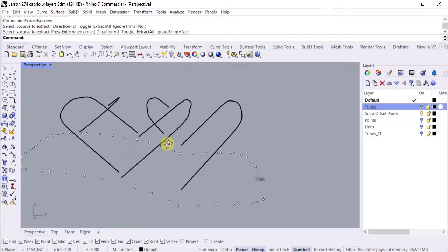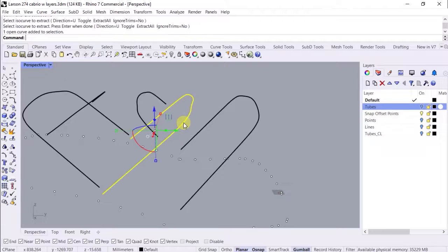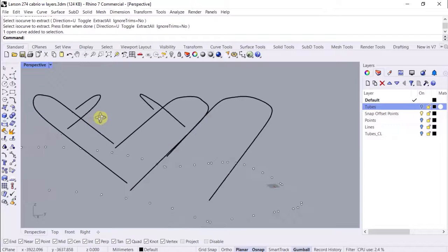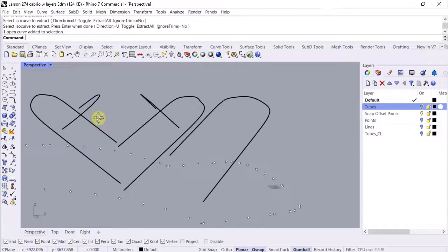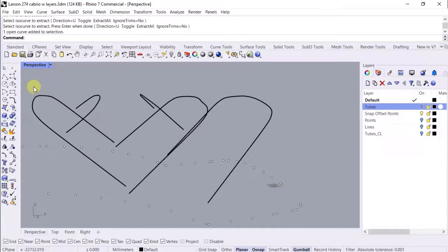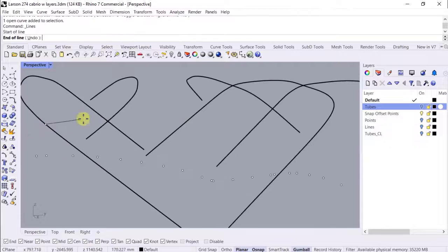To get these to the correct length for the Bimini canvas panels, we need a horizon line. We're going to draw a horizon line based on visuals. Right-click on the polyline icon to get line segments. Draw this down the edge of the Bimini.